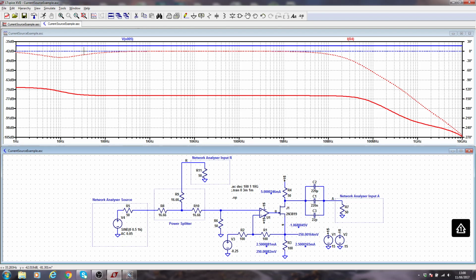No surprises, we only got resistors here. Sure enough, everything's dead flat. The level is not 0 dB because the AC is a small number, and also because we have some resistive losses, but the phase is flat. If there was impedance mismatch here, it wouldn't show up on this graph.